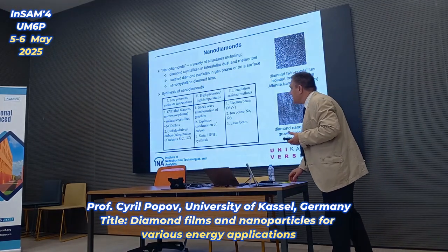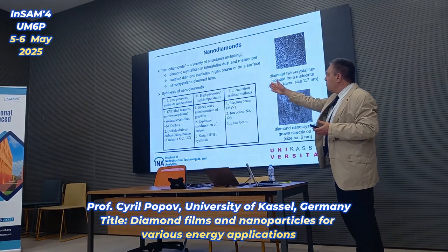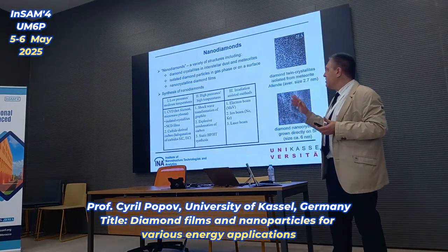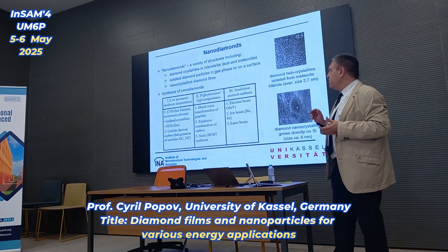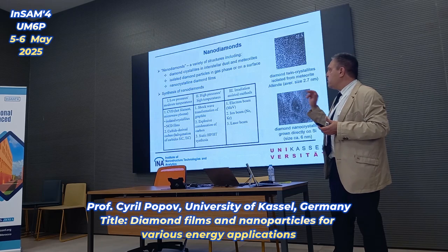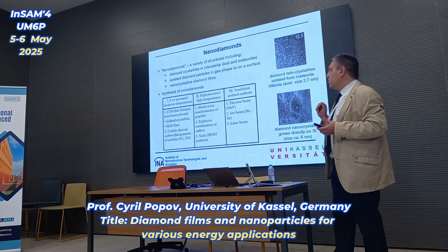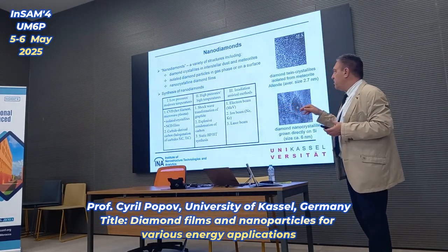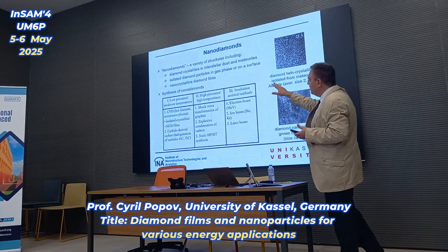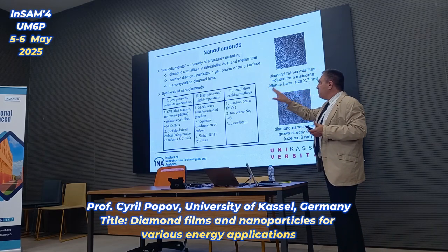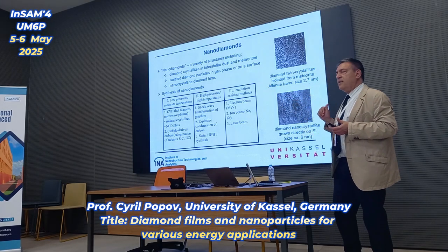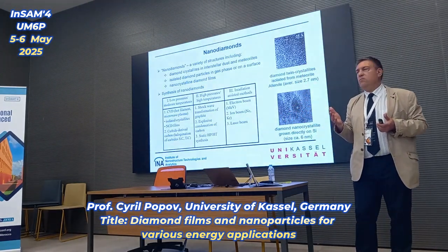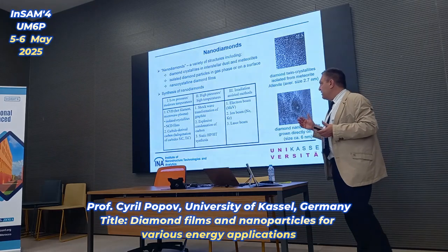So, how they are synthesized, I mentioned already from the first group of methods, the low pressure and moderate temperature group of methods, the chemical vapor deposition, where we can prepare isolated crystals, but also nanocrystalline diamond films. There are some more exotic techniques, I will not pay attention to them. The second group is the group of high pressure and high temperatures. So the static high pressure, high temperature method was the classical one, used for preparation of synthetic diamond.